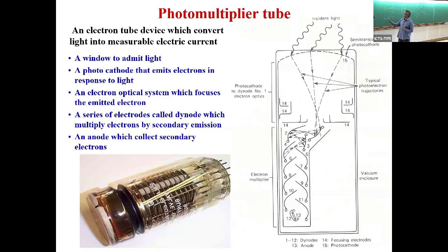Okay, this device conventionally has three parts. One is the glass, you see. This is the convention, what is the photocathode? On the glass, you have a photocathode material where the incident photon is converted and gives you the photoelectron. This photon is in the visible energy range, 2 to 3 electron volt. This is what I call the photoelectron, and this electrode is called the dynode. Here you have an external electric field, roughly a few hundred volts, and the electron will be accelerated here.